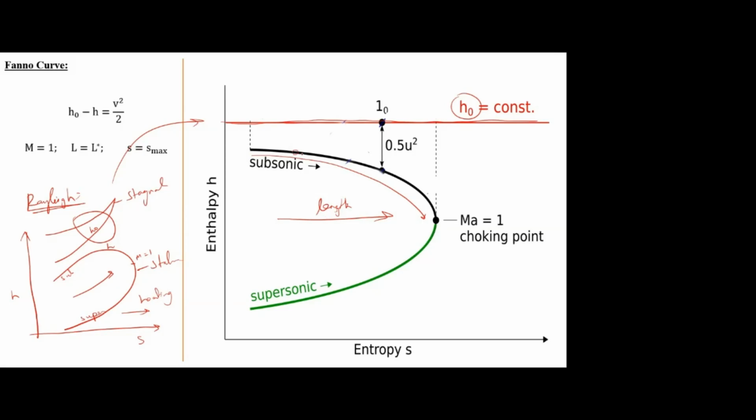If you keep on increasing the length, maybe from 0.3 to 0.5, further it will reach 1. If you further increase the length, greater than L max, then this 0.3 will move towards 0.2. Then supersonic, maybe 3. If you keep on increasing the length, it will go to 2. Finally, it will reach 1. If we further increase the length, there will be a normal shock wave that will be subsonic and again sonic.